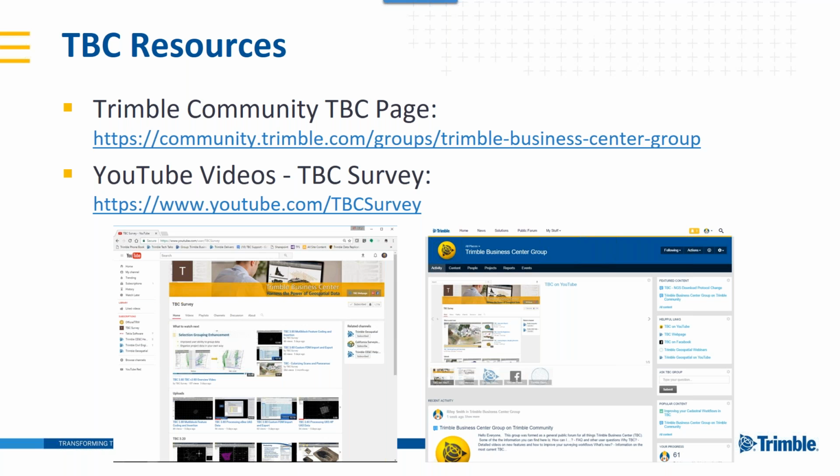So there's one about dynamic text up there, and I wasn't sure. Is text dynamic text styles? Is there an option to make it dynamic, so it scales up and down as you change your plot scale? If you change your plot scale, like through the project settings in TBC, that will change it. But there is no specific change-on-the-fly kind of thing, like a plan view change on the fly like Civil 3D. But it does actually change as you change scales.